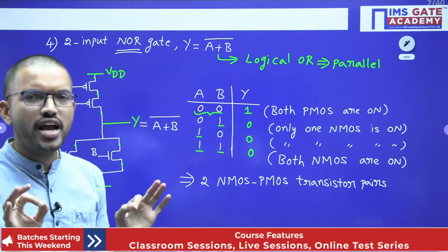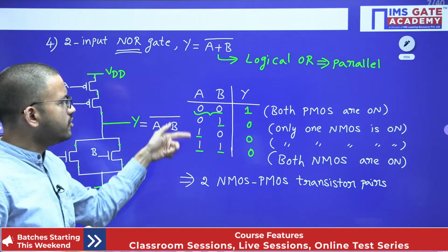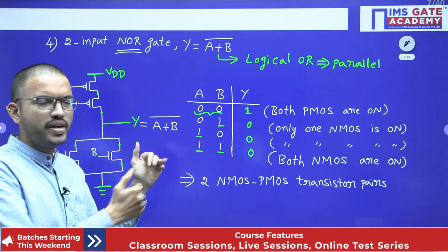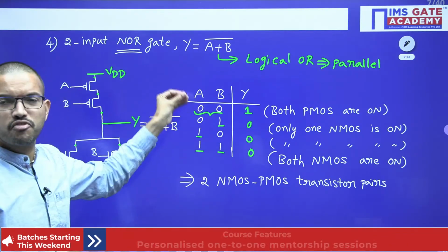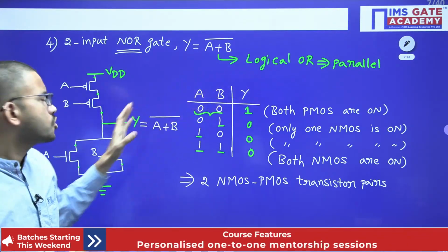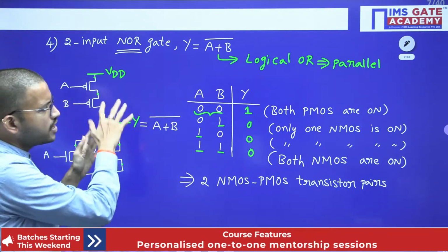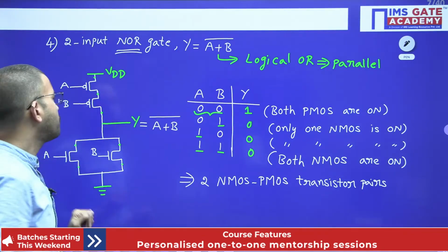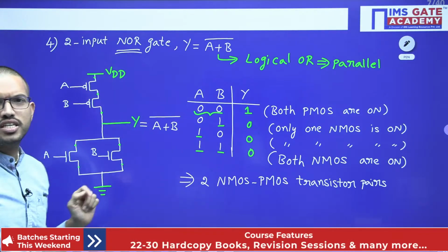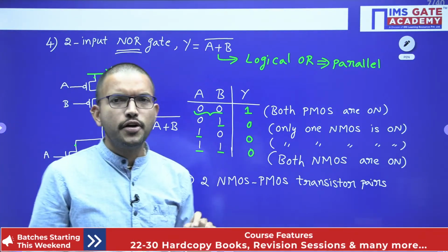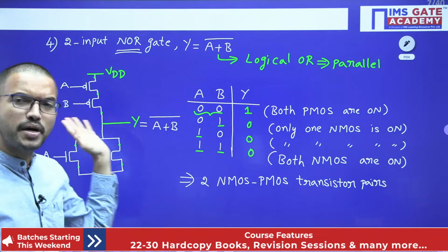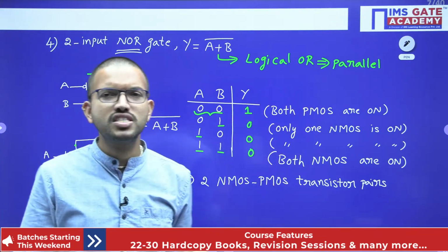And in fact, in general, we will change the inputs based upon the requirement, or in general, these inputs will come from the output of some other circuit. So even because of all these considerations, during the entire operation of the given circuit, no single transistor will be permanently on. That is the beauty of the CMOS logic.